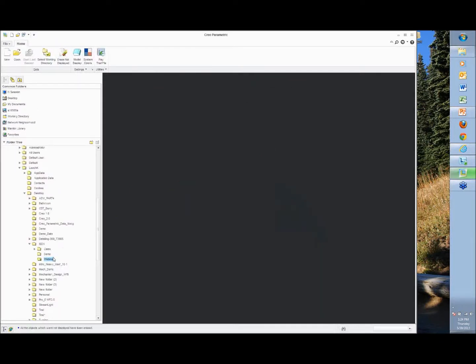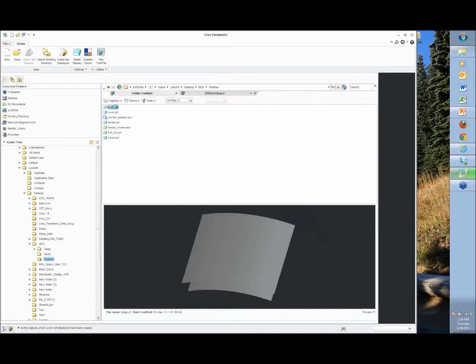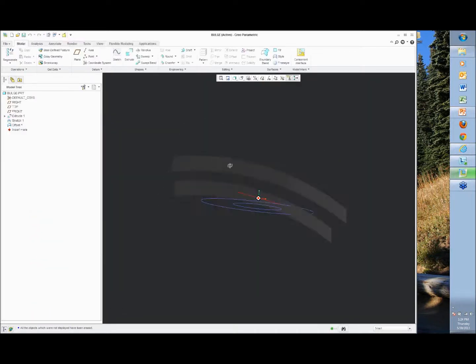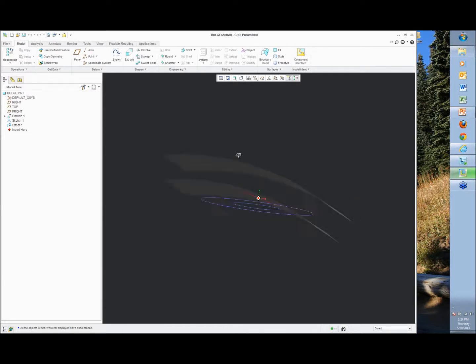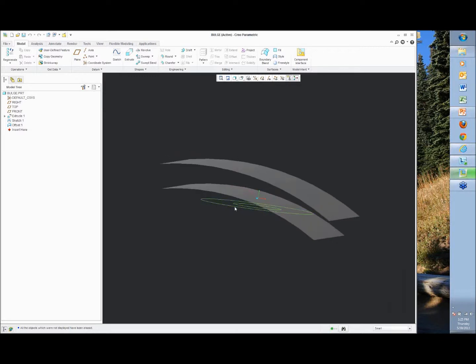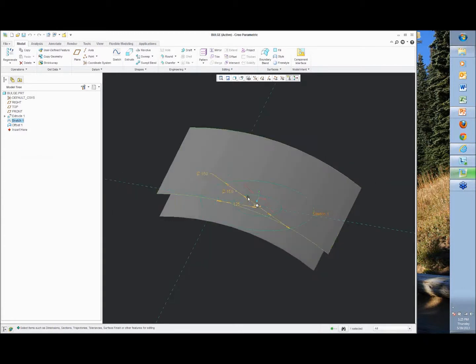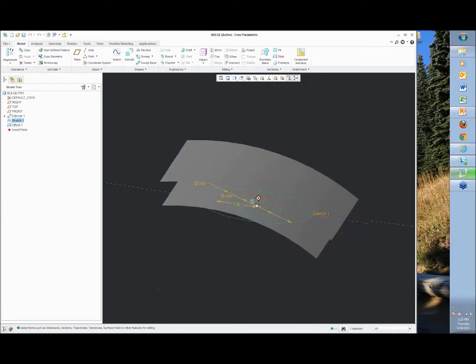A couple more little examples in here. One is where I made some simple surface parts, but basically if this was a big cover or something and you want to put a dimple down inside of this, this is how you go about doing it, right? So I've got a simple sketch down here, two circles. I'm going to project them up, the big one on top, the little one onto this one, and then I'm going to connect and make a bulge out of the whole thing.